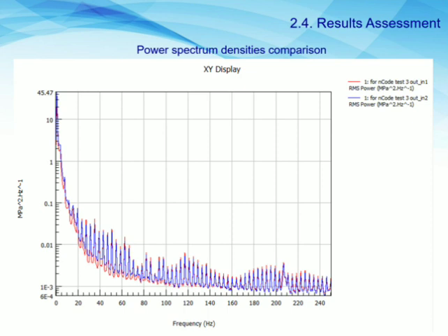The GlyphWorks Frequency Spectrum glyph can easily calculate the power spectral density from time domain data. This glyph performs frequency spectrum analysis, autospectral, on time series data using a fast Fourier transform algorithm. Power spectral densities of the measured and the edited signals that are compared in this slide have a good correlation. These two trends were very similar because editing doesn't introduce any anomalous peaks.